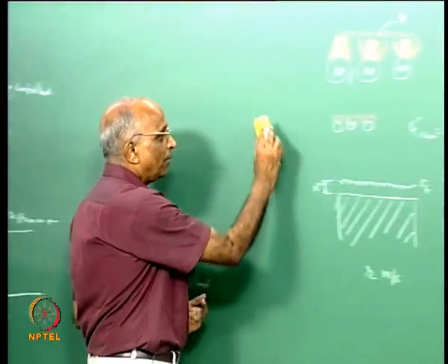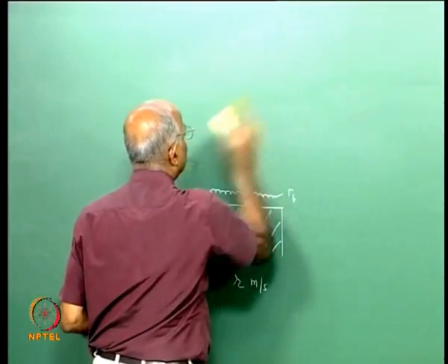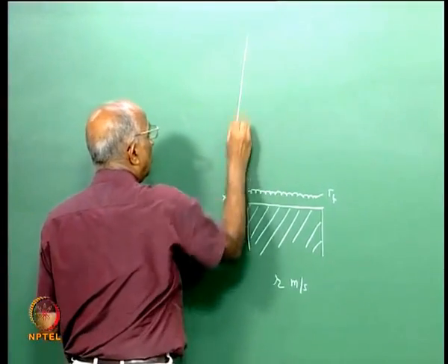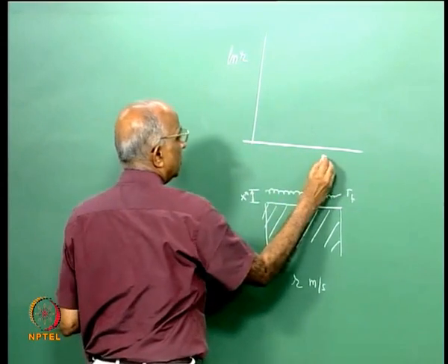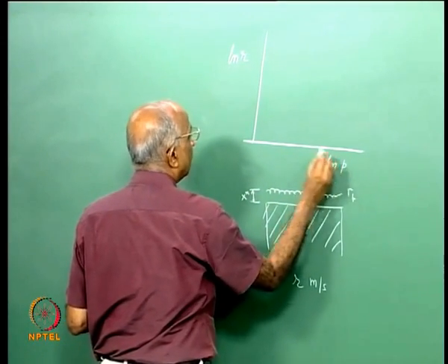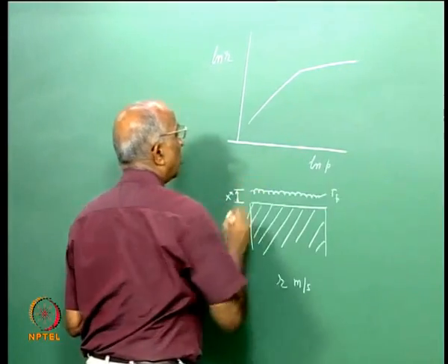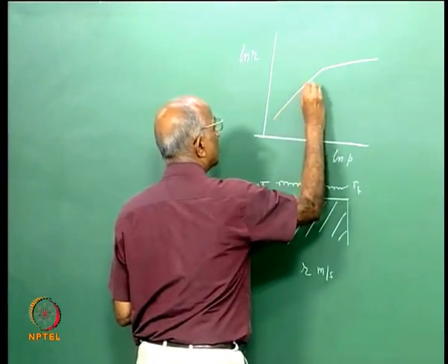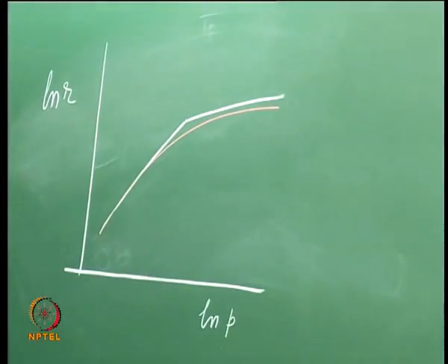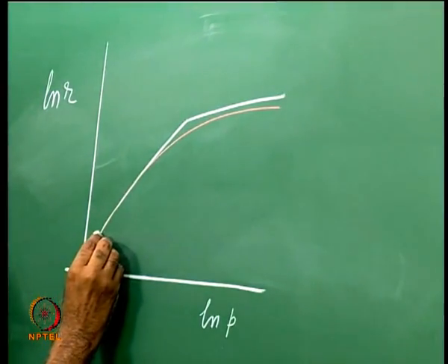It is different from double base propellants in that if I were to plot the logarithm of burn rate versus the logarithm of pressure, I have a high value of n here, and a smaller value of n over here, or rather the burn rate goes something like this. Whereas what did we have in the case of double base propellant? It was just the opposite.